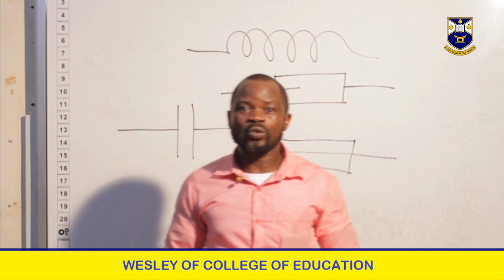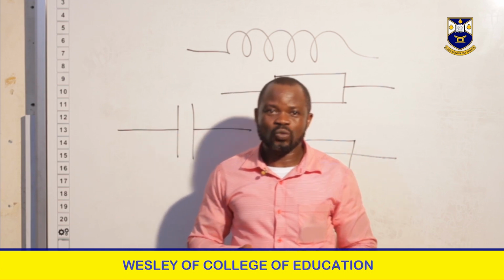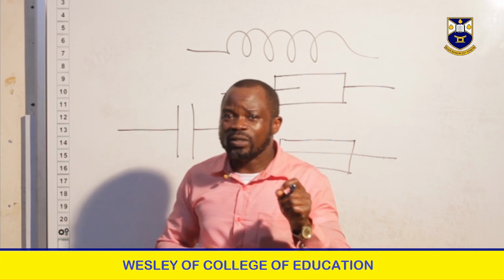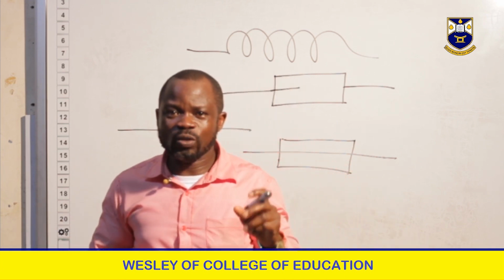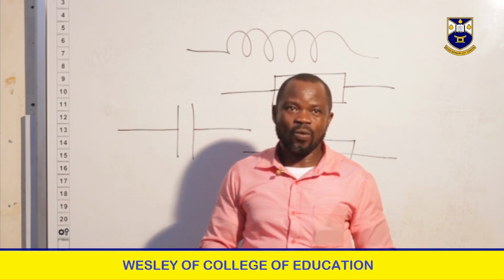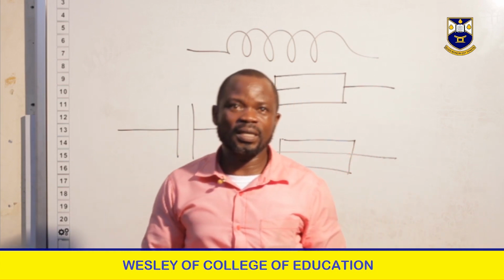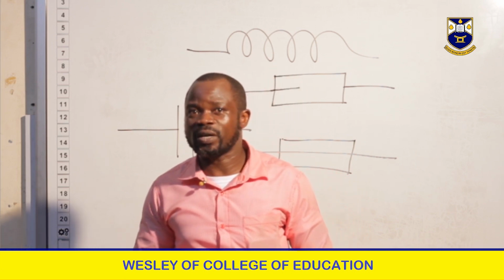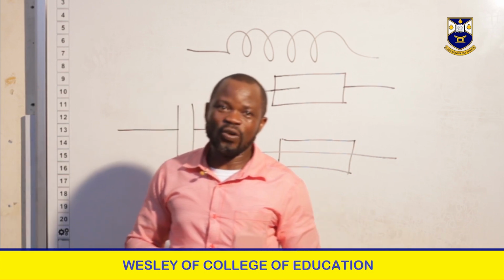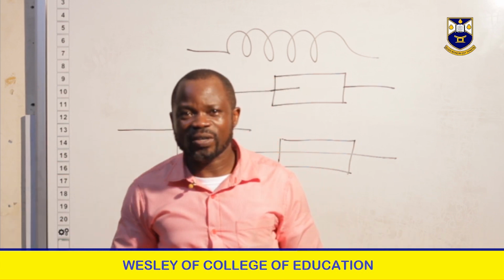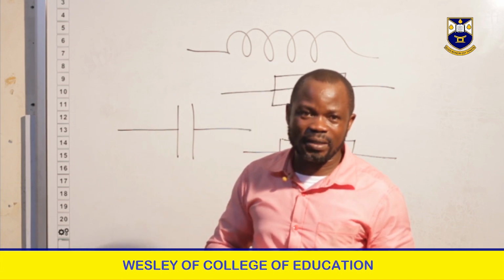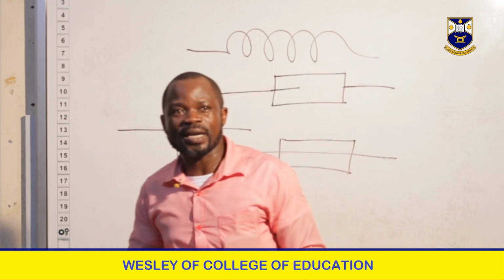Suppose we want to activate one of the red pixels. The two electrodes leading to the pixel cell put high voltage across them, causing it to ionize and emit ultraviolet light. The ultraviolet light shines through the red phosphor coating on the inside of the pixel cell, and the phosphor coating converts the invisible ultraviolet into visible red light, making the pixel light up a single red as we see here.